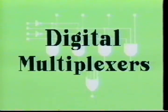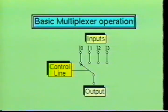The digital multiplexer is a combinational logic circuit containing 1 to 4 control inputs and 2 to 16 data inputs for each data output. Some multiplexers even provide complemented data outputs. Basically, the digital multiplexer performs the function of a single-pole multi-position switch in which one of the data inputs will be connected to the output at any one time.